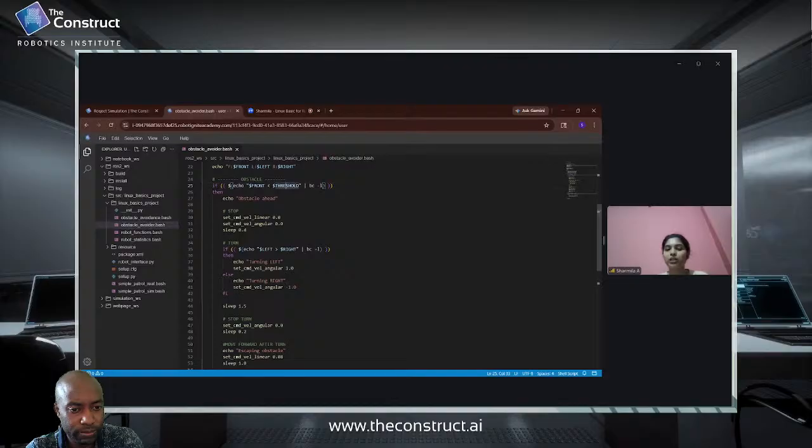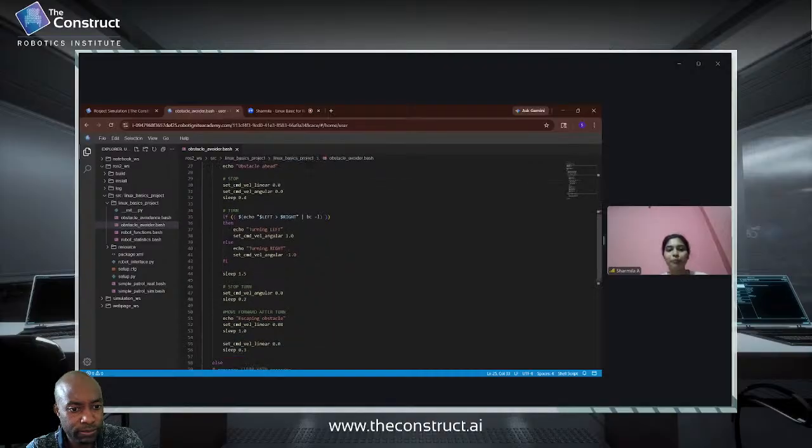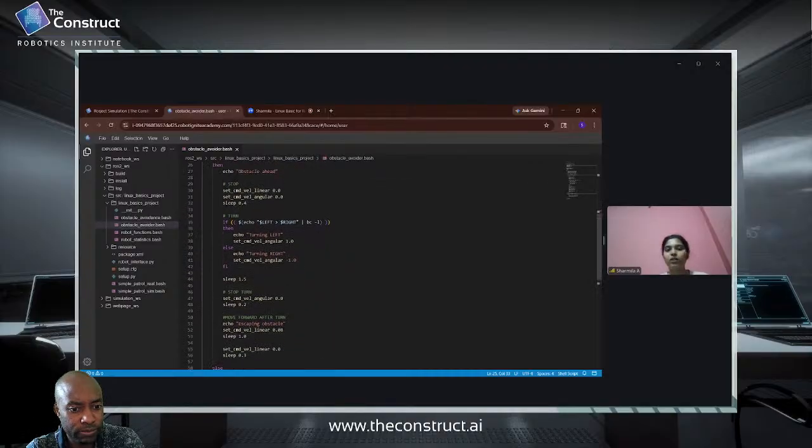And if an obstacle is detected, it will compare which has more distance, right or left, and move accordingly. Then my case 3 is for the turn, where it checks whether left is greater than right, or which one is greater, and it will move accordingly.